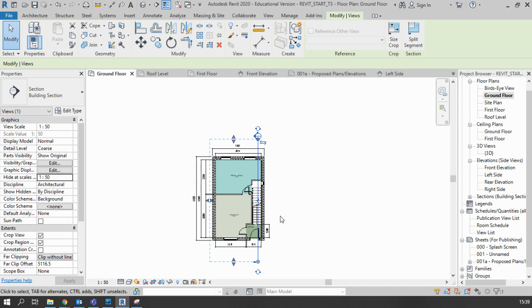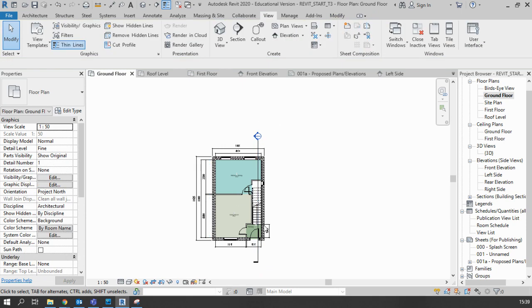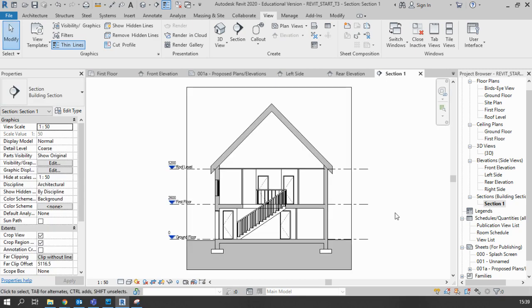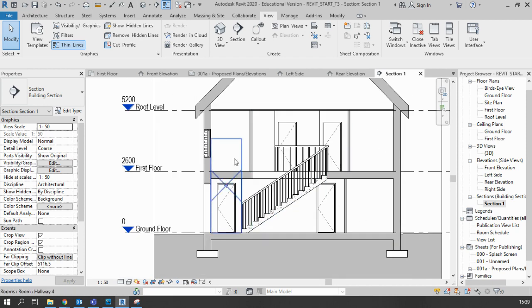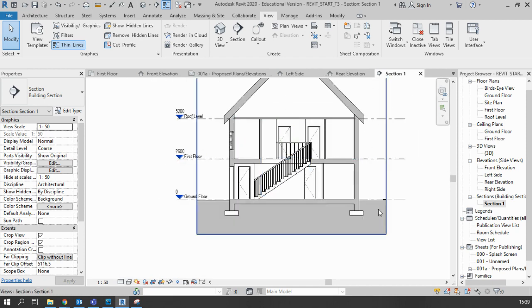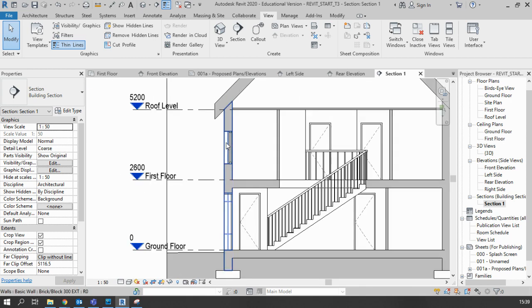Now, where does that go? In Revit, once you create a section, or any new view, it creates that view in your project browser. So now you should see Sections appear in your project browser. You click on that, extend that, and there you go. That's the section you just created. That's a cut through your building. That shows your stairs, your rooms, and then your roof and the ceilings and that kind of stuff. It also shows your windows and the brick details.